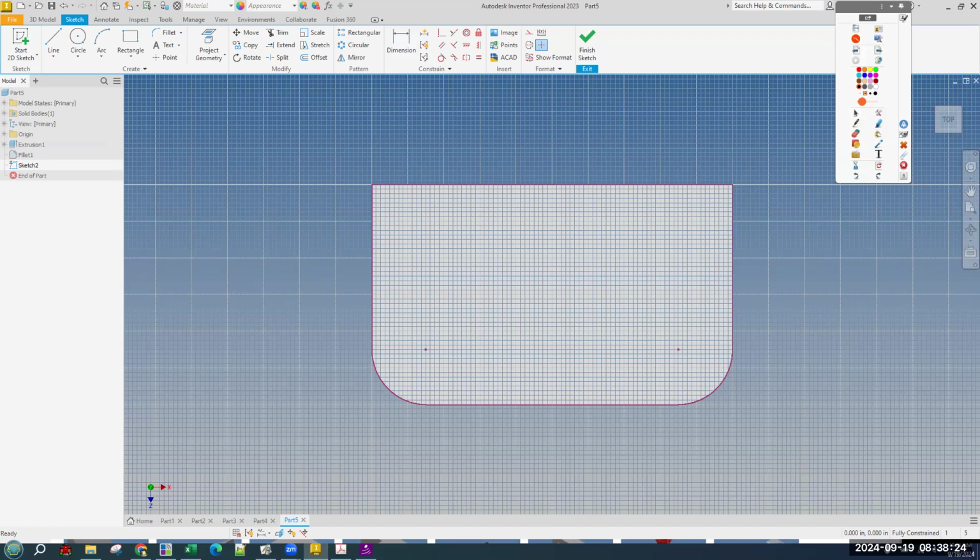There you go. Okay, so like I said, and I'm happy I wasn't mistaken, they didn't change it. We get this snap here, which will make it easy. We just need one circle on this side. That is 1.5, which will make the circle and dimension it. Oh, excuse me, the diameter of the circle is only 1. My mistake.